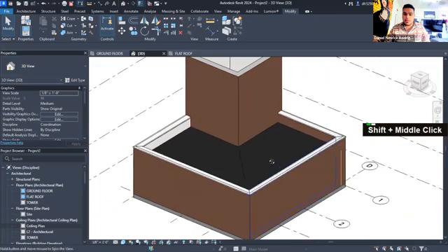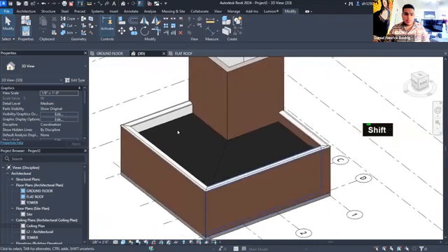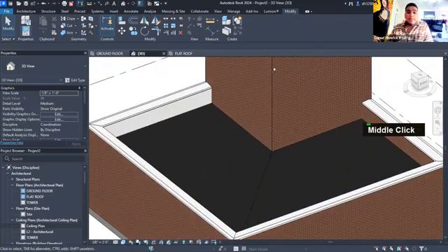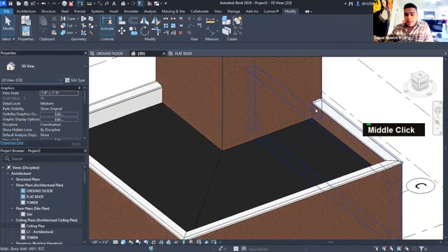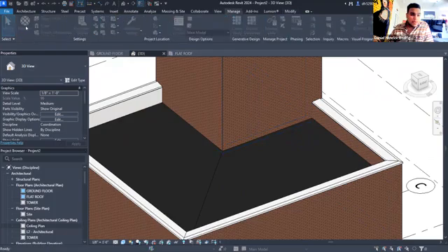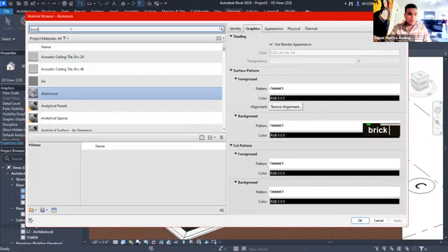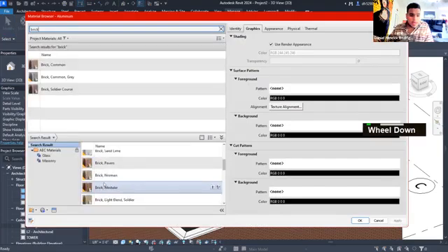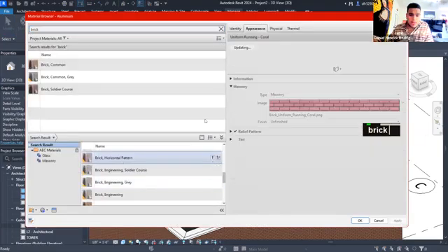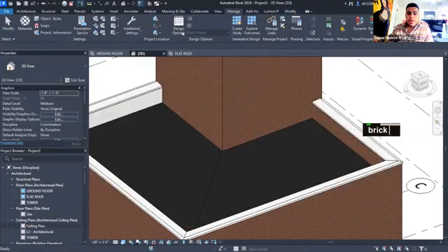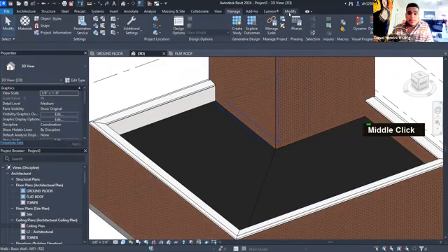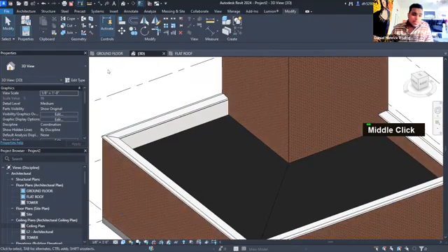All right, let's go ahead and do that on all of these walls. I'm using the regular brick here, but if you're using a different brick, all you're going to have to do is go to Manage, Materials, and just like you loaded in the brick before, you're going to load it in here. So look up brick, pick whatever brick you want, load it in, and that's going to allow you to use it in the paint tool. Okay. Well, let me just get back to doing this.